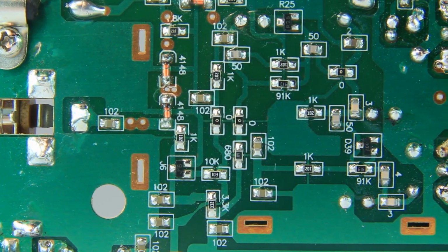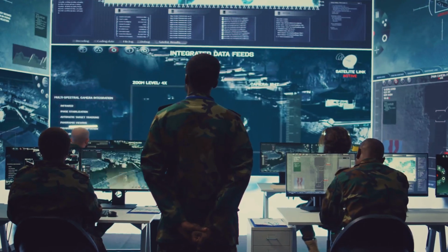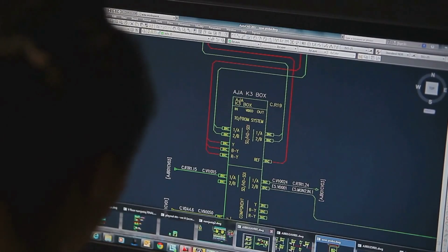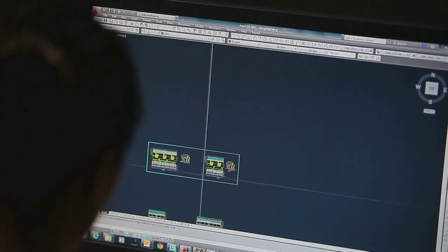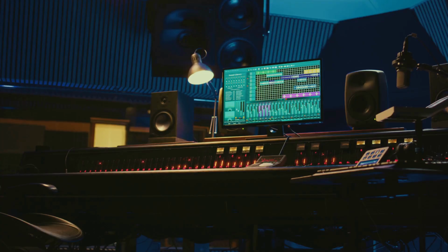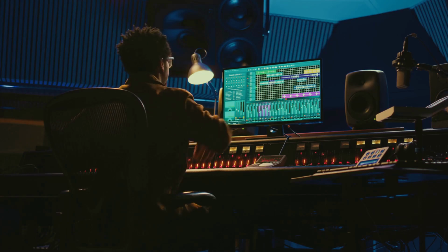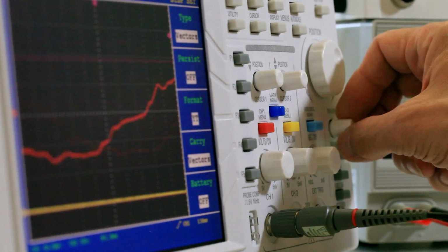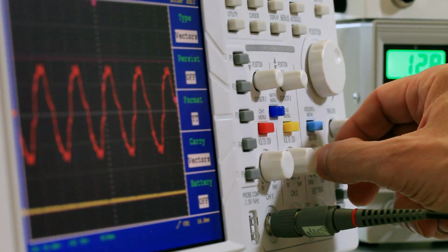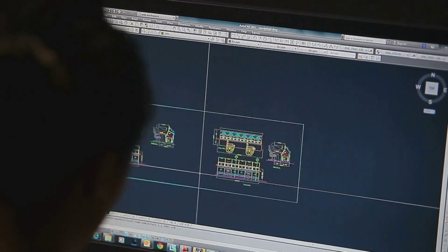Section 4. Identifying the enemy. Defining excitation sources. No battle plan is complete without knowing your enemy. In EMI simulation, our adversaries are the sources of electromagnetic noise. These can be anything from high-speed clocks to switching power supplies. We need to tell CST Studio Suite exactly what kind of noise these sources are generating. Are they digital signals with sharp edges? Are they sinusoidal waveforms? What's the frequency? The amplitude? The more information we feed the software, the more accurate our simulation will be.